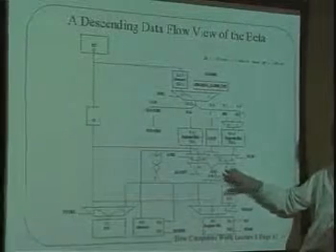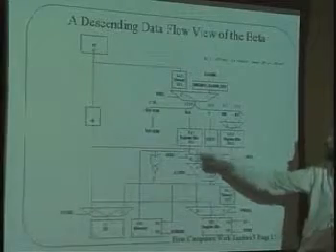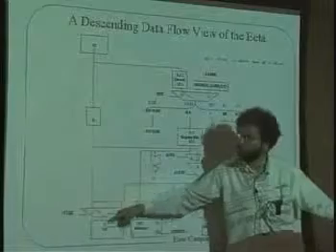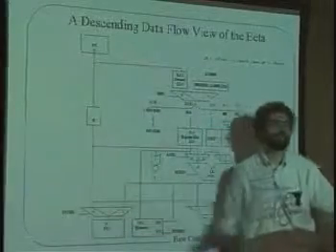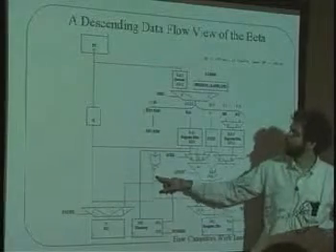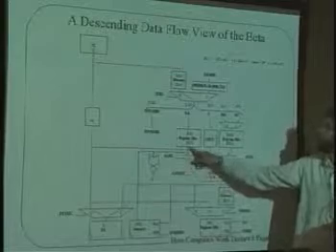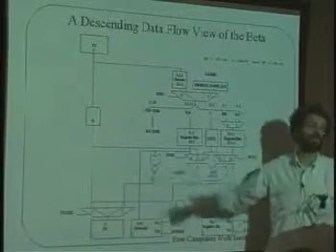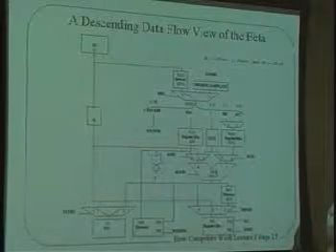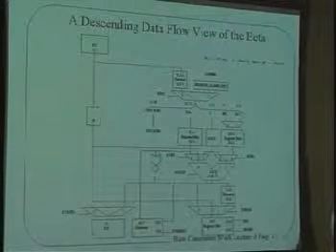So the ALU will be told to do an add, and the result of the add of PC plus 1 plus C will be spit out here, and that will go into the PC instead of PC plus 1. And the control over that will be whether or not this little Z here is high or low. In other words, whether the data that's coming out of register A over here is all zeros or whether it's not. And that's how we're going to do a conditional branch. So both those occur at the same time?